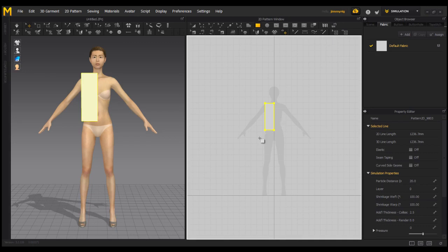So once I have this rectangle, I am just going to mirror copy the other one. So let's grab our transform pattern tool and press Ctrl C and Ctrl R on our keyboard for creating a symmetrical copy. Since these are only two rectangles which will obviously change some more, we want to change this to be the same on both sides.